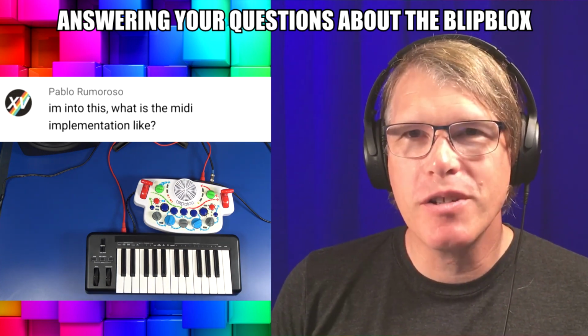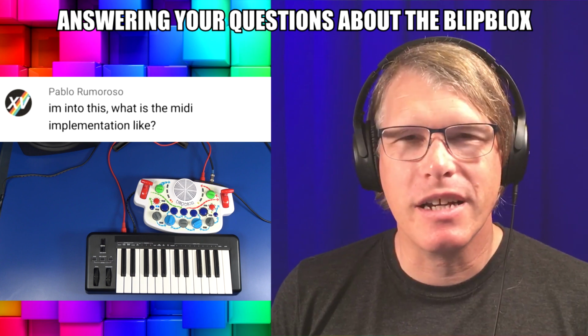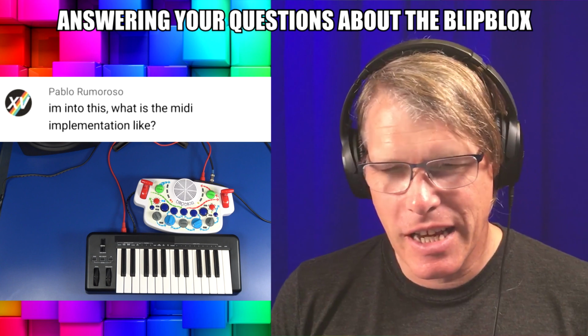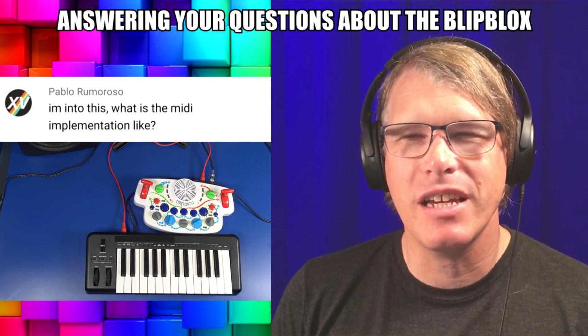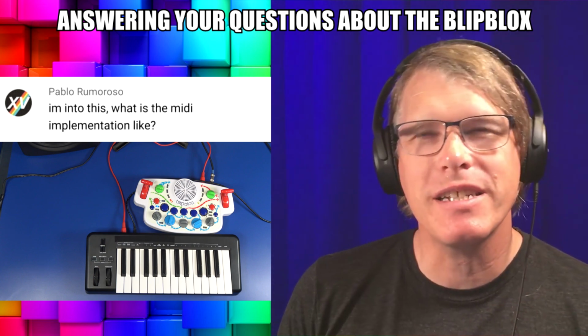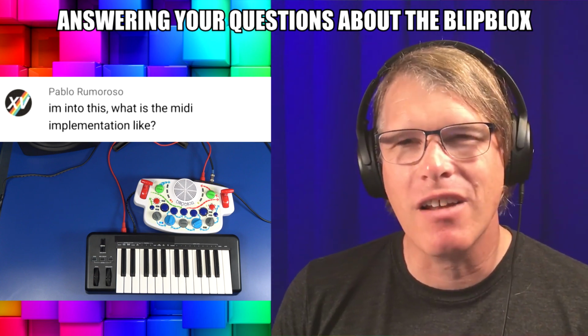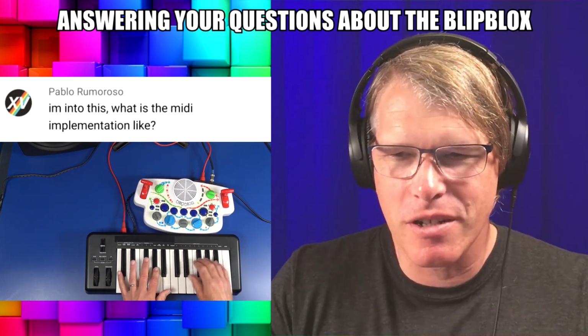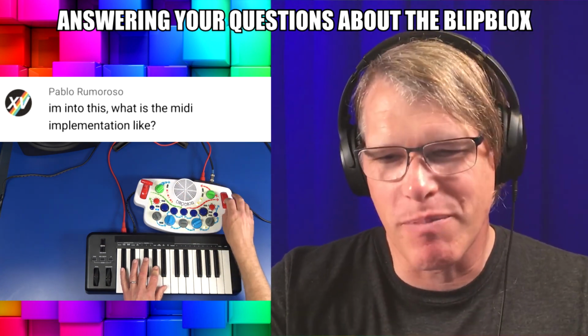Blipblox also does respond to MIDI start, stop, and sync commands, so you can synchronize it to drum machines or sequencers, and that's sort of the extent of the MIDI implementation. It does not respond to MIDI CC, so you can think of it more sort of an analog synth, where you can basically sequence out the sequence in the notes, and then you can adjust it manually using the big fun controls.